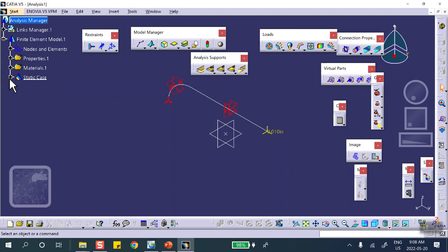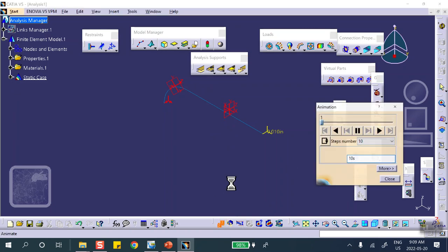But because of the nature of the problem, if rotation about Z is actually free, then this can go like that. It has nothing to do with the symmetry. The symmetry we did right. But because rotation about Z is actually free, it can move as a rigid body like this. And you can see that it pivots about that. You won't lose marks for symmetry. The symmetry is correct, but you can't finish the problem. You didn't finish the problem because you didn't know what to do. You lose marks on that side. Your symmetry was okay, no problem.